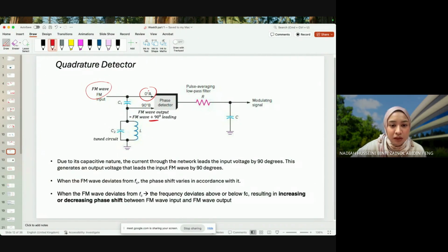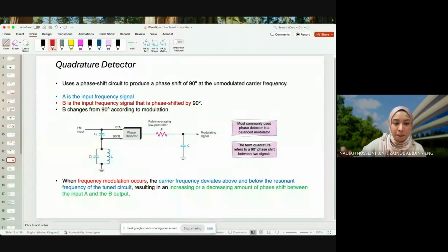These two signals are fed into our phase detector. We multiply these two signals together, and the difference tells us how much difference there is between the two. Then it passes through the low pass filter, and hopefully we will get FM or something.